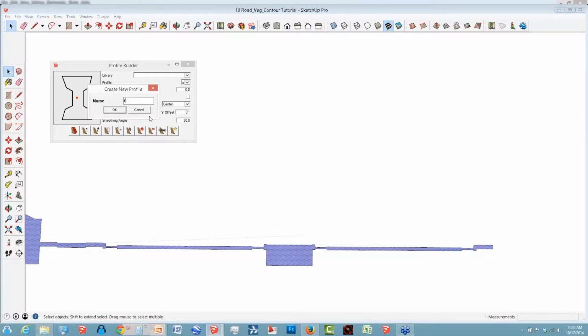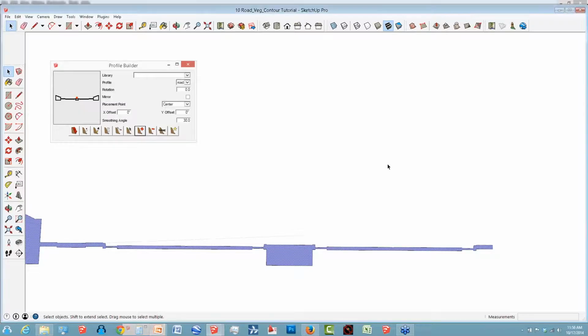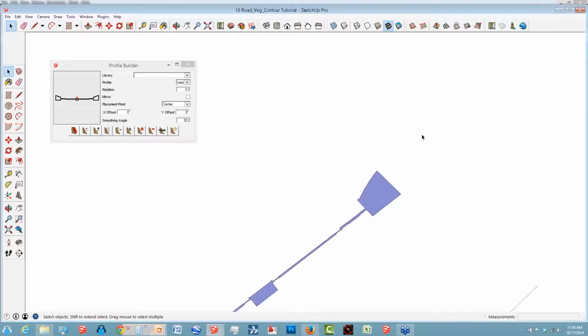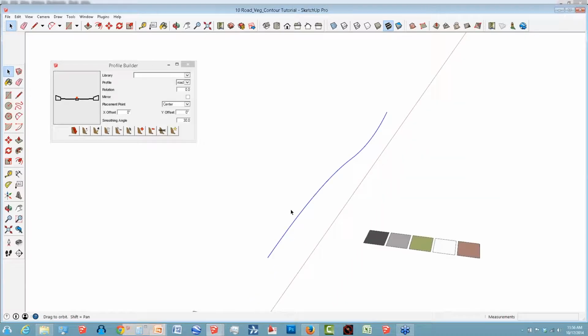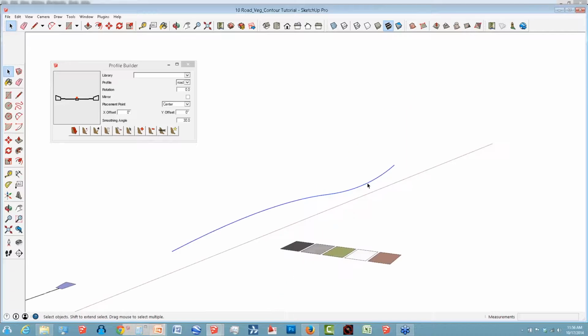So very simply put, how does this work? Just to show you the power of this tool and what SketchUp can really do with all these. And pray for no crashes. You just never know. Select what I ended up selecting here, and you'll see it in a second on your screens, I selected these two arcs. They are actually welded together. I'm going to extrude that road profile along that arc. Might take a second or two or three or four.